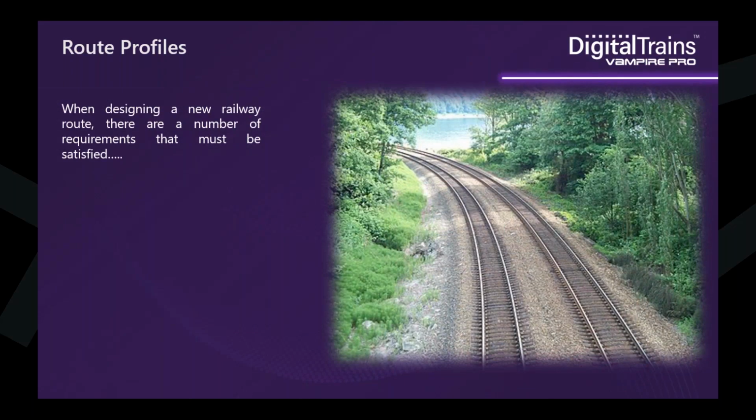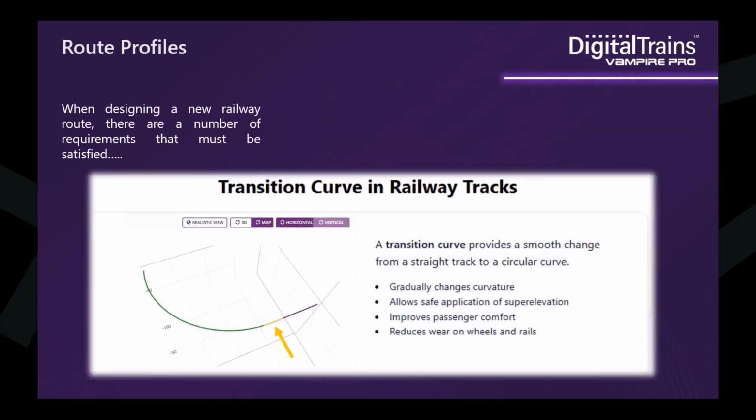So when designing a railway route, there are many requirements which must be incorporated to ensure a smooth ride at the intended line speed. These must also be combined with operational and geographical constraints. The alignments, for example, must pass through all required stations, enter and exit in the correct directions, and avoid existing built-up areas and natural obstacles like steep terrain, large lakes, etc.